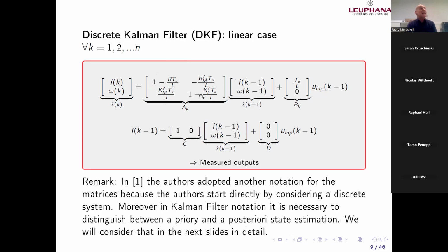This states a not observable system. Do you remember the concept of observability? Observability is based on the connections between the states. If the matrix is an identity matrix, or tends to an identity matrix, we don't have connections between the current and omega, or x1 and x2.